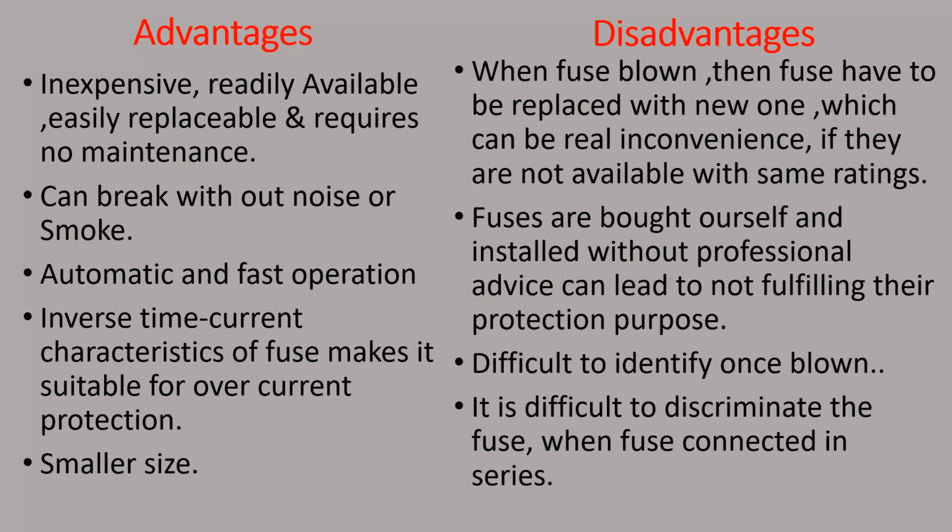That is a disadvantage. Fuses bought by ourselves and installed without professional advice may not fulfill their protection purpose. It is also difficult to identify once blown, and difficult to discriminate the fuse when fuses are connected in series. So these are the disadvantages of the fuse.